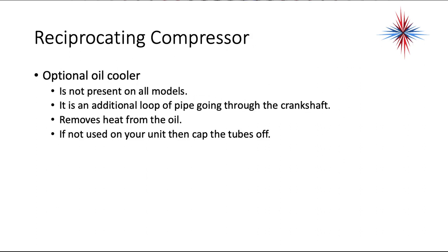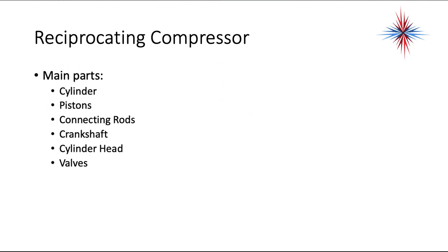Sometimes there's an oil cooler. It's not present in all models. All an oil cooler is, is an additional loop of pipe going through the crankshaft. It removes heat from the oil. If it's not used on your unit and it's there, just cap the tubes off.